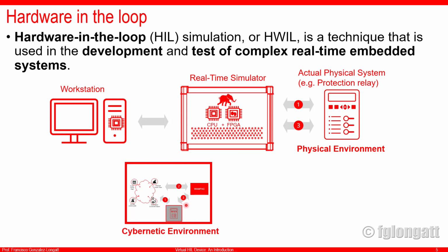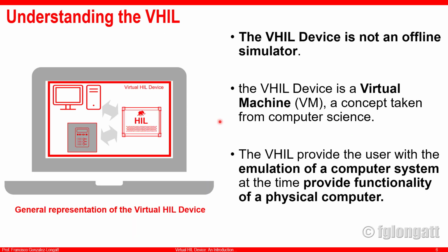Okay? However, what is one of the big issues? Real-time simulation is very different from offline simulation. In offline simulation, time is not a problem. In real-time simulation, hardware in the loop, time is a very important issue, okay? That is the reason we need to use this supercomputer, let's say a very fast computer, the real-time simulator. But those real-time simulators can be expensive. And that is where